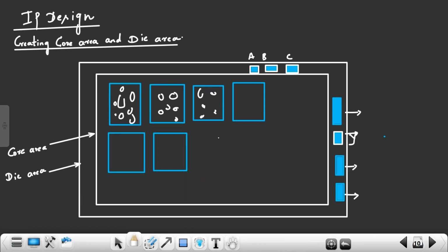If I don't purchase these macros from a vendor, then I have to do the physical design and write the Verilog code for this. That is very difficult. For that reason, in every design we will have a few things called macros. Macros are complex cells which are already optimized. We directly purchase them from a vendor and use them in our design. So we use memory macros.